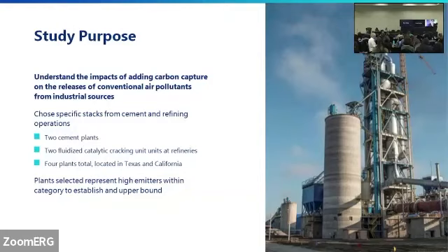So some studies would only put a minimal amount of pretreatment on, a polishing step, sodium hydroxide. Sometimes they would just say, well, we don't know enough about what happens with particulate matter, so we're just going to assume that nothing happens to remove that particulate matter in the absorber. Or we'll make an arbitrary assumption that NOx goes down by 50%.